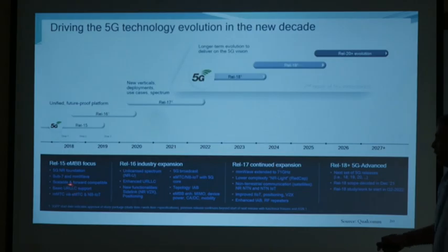And 5G also introduced scalable numerologies. What does numerology mean? The 5G technology is based on OFDM system. So OFDM in 4G, the subcarrier spacing of the OFDM is fixed to 15 kilohertz only. But in 5G, the subcarrier spacing is changeable. So it can be 15 or 30 or 60. It can go like this. So it's called numerology in 5G. So the flexible numerology is introduced in 5G.